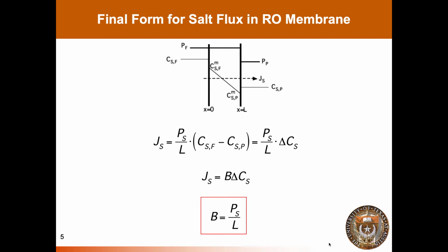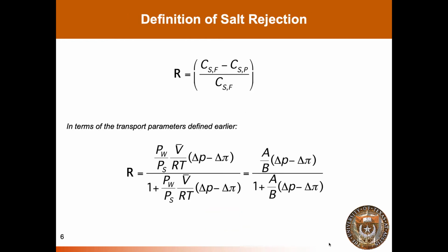And we can see then that the empirical performance equation for how salt flux depends on salt concentration is simply related to the salt permeability, which in turn is the product of the salt partition coefficient times salt diffusion, divided by the thickness. This will, like the water case, be the dry thickness of the membrane effectively.